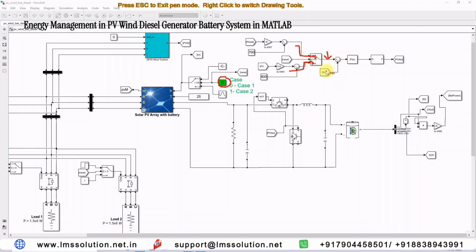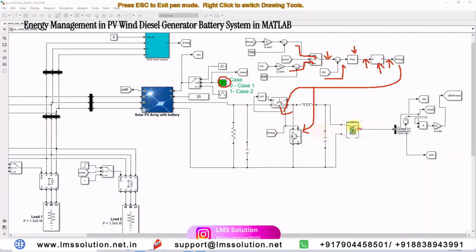It is compared with the battery current and processed by a PI controller. It will generate the duty cycle. When we process it through the pulse generator, it will generate the pulses. These pulses are given to these two IGBTs to charge and discharge the battery based upon the reference current of case 1 and case 2.